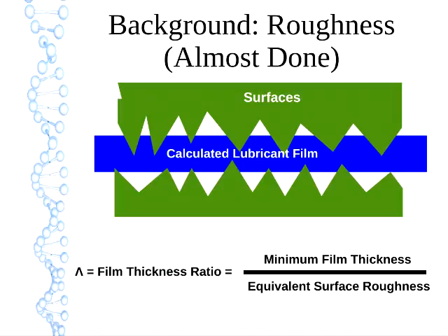If you've got a very coarse surface finish, say some cast iron straight out of the mold, 2 microns is not really anything. But if you've got a ball bearing with those highly polished surfaces, 2 microns is a lot.